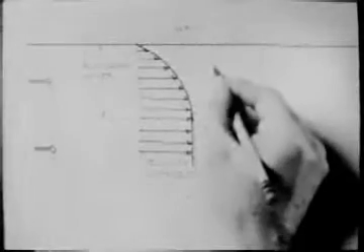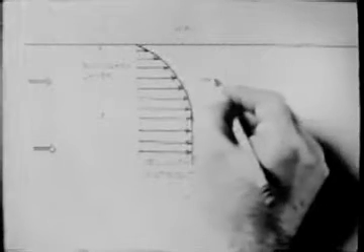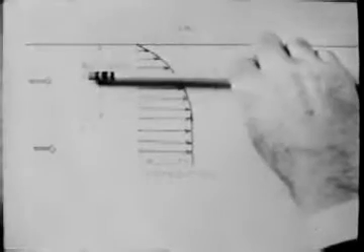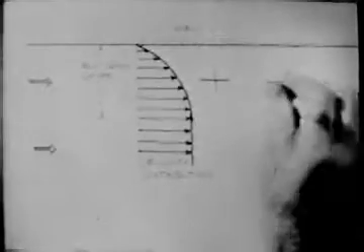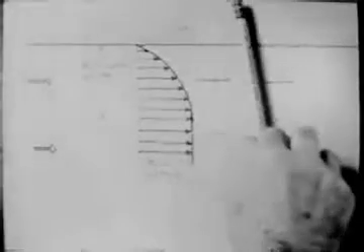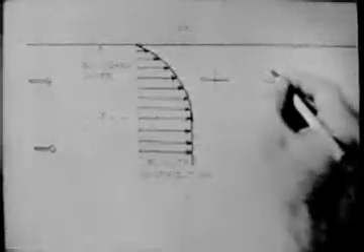Let's look at a fluid cross. One leg moves downstream parallel to the wall, while the other leg rotates because of the non-uniform velocity distribution. So there's a net vorticity, and the vorticity meter spins.